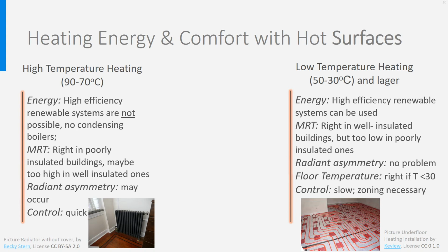But is it still comfortable? Well, people love warm walls and find floor heating very comfortable as long as the temperature is around 24 degrees C, not exceeding 30 degrees, for less than 10% people dissatisfied. So that is good. However, the mean radiant temperature, MRT, should be kept in the right range too. That is where it can go wrong.